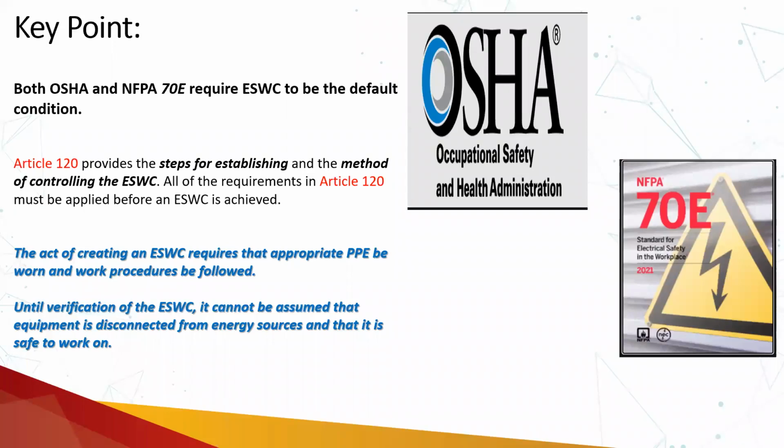So if we are doing that verification, it is going to indicate that there is residual charge there. In establishing an electrically safe work condition, it says that all the stored electrical and mechanical energy should be removed before going into the step for the verification.